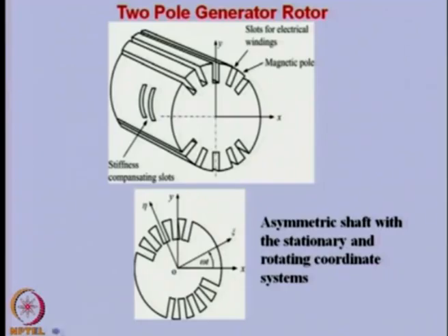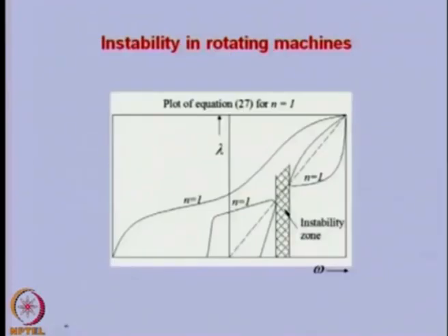And the Campbell diagram which we drew earlier, in which this was the spin speed, this was the whirl frequency, we will find that in a certain region the natural frequency will be complex, and these are nothing but unstable zones. So, this analysis we will study subsequently during the study of instability in rotors, and the rotor will be highly unstable in these regions.